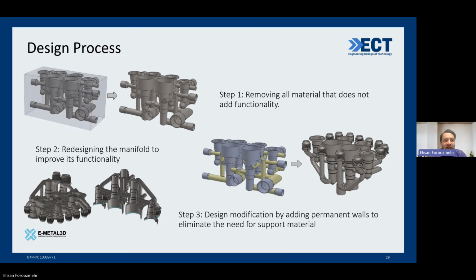So just have a look at what happened. They defined the actual passages and tried to optimize the galleries. As you can see, all the vertical and horizontal pipes are changed into nicely and smoothly shaped passages. Then they tried to remove extra material and use it to self-support the ports, and also make it strong enough to hold itself, because obviously it's going to take a lot of pressure inside.